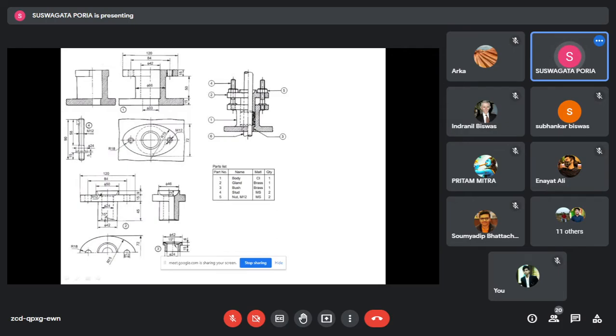This stud, if you move this stud in AutoCAD, suppose this drawing is in AutoCAD, and you place it, if you match this center line and this center line, or if you use the coordinate system, then also it will be perfect. You can bring it here, then use the coordinate system, give the coordinate, and it will be perfectly placed with it.